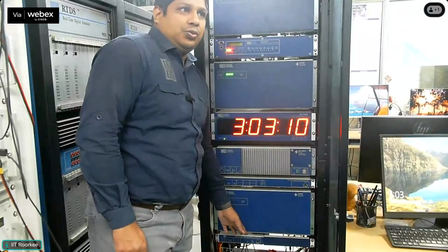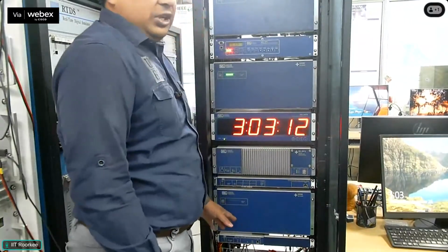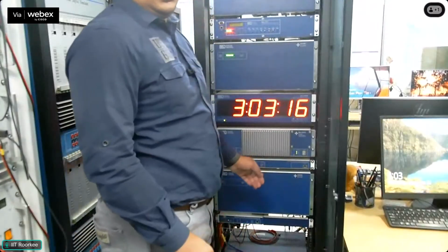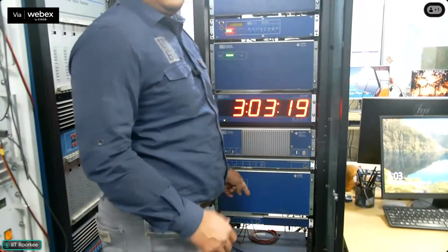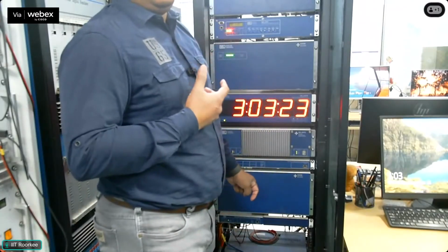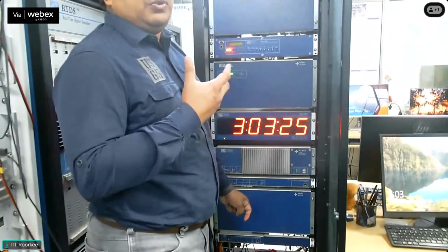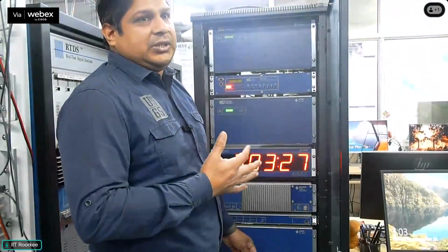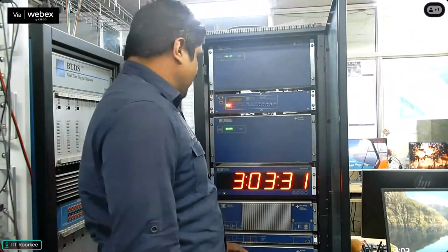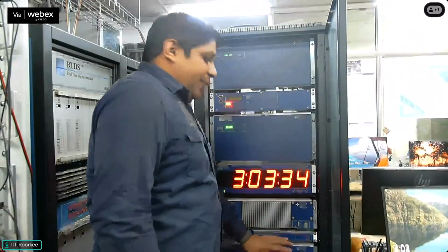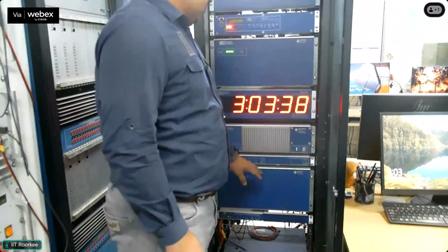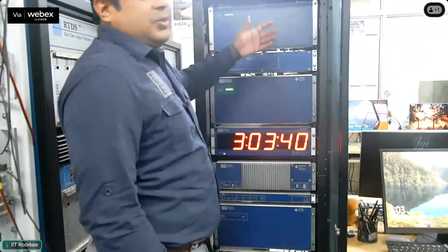We give three voltages and 3 currents to this amplifier. We can give 6 currents also based on our function. If we are only working on the fault and protection functionality, we generally give 6 currents. Here we are giving 3 voltages and 3 currents, and after amplification, we give them to these PMU devices. I will show the connections in the backside.